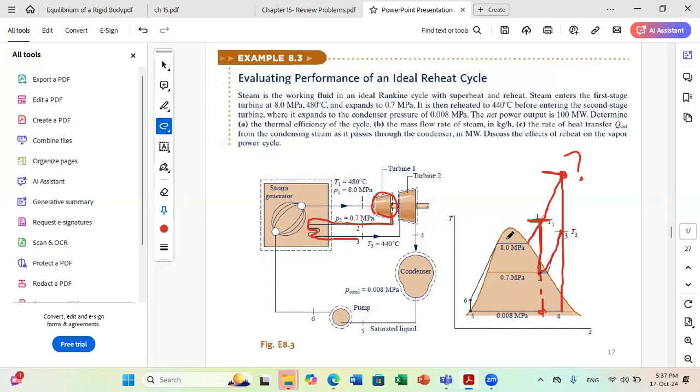Of course, how we decide on the limiting temperatures, or how much we should heat, depends, and we can do a parametric study. What is the temperature needed, for example, to reach the desired quality? Let's say we recommend a minimum quality of 90%.